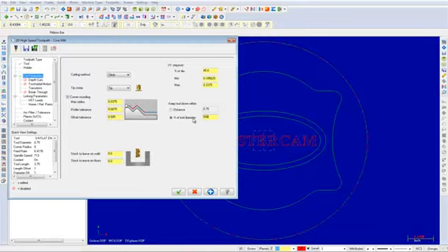I will now take a brief moment to explain a few of these parameters. Corner rounding replaces sharp corners with arcs for faster and smoother transition in tool direction. Max radius is the largest arc that you will allow Mastercam to insert to replace a corner. Larger arcs will create a smoother toolpath but with greater deviation from the originally programmed toolpath.